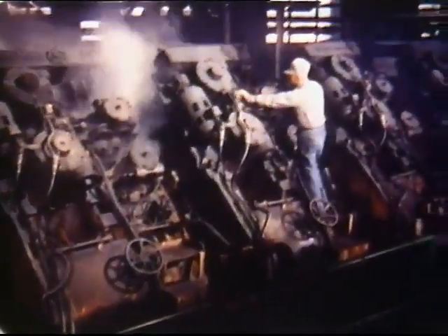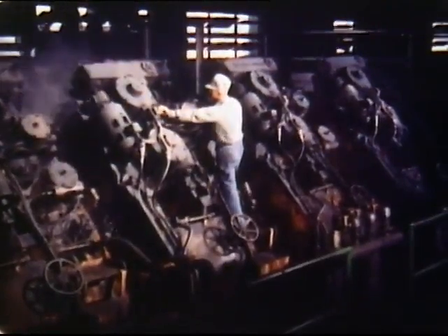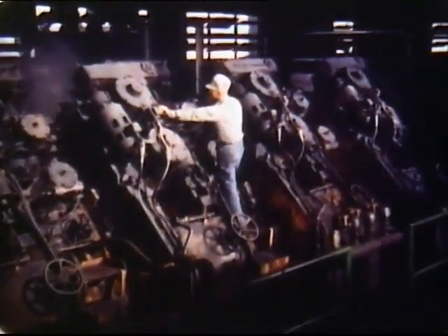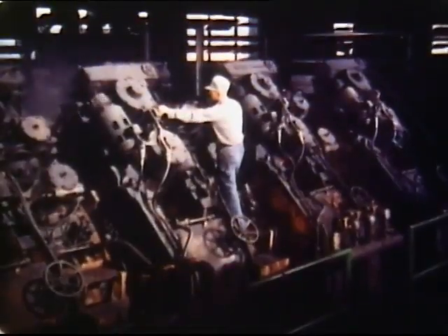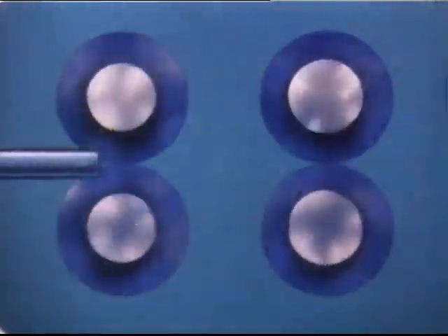It has 9 pairs of semicircular grooved rolls so arranged at right angles to each other that the rolls alternately engage one side, then the other of the shell's outer surface. Reduction of the shell's diameter over the mandrel is the first step. The first 2 sets of roll stands do that.